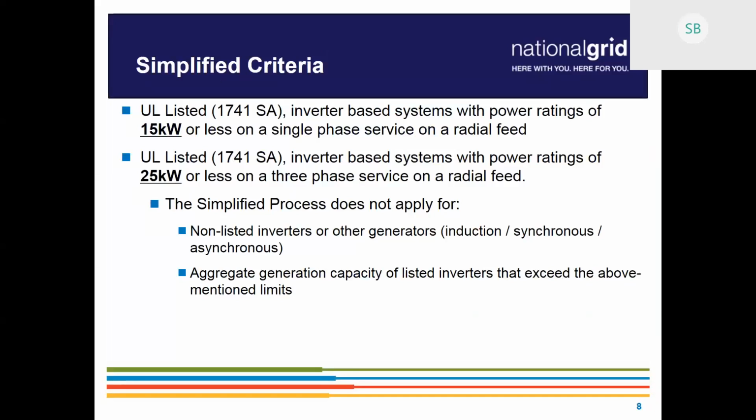So this first slide is really what defines the application as simple. We're looking at if it's single phase, it's 15 kW or less, and if it's three phase, 25 kW or less. And it has to be the UL 1741 SA inverters. So that's really simplified, and as you'll see in the next couple of slides, it's a shorter process than the standard one.